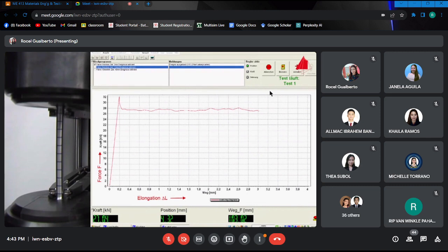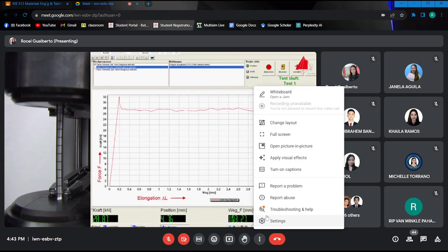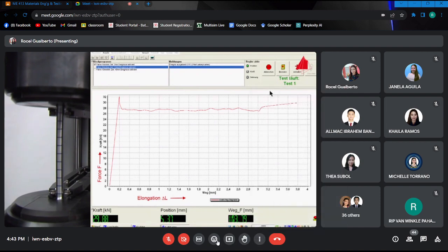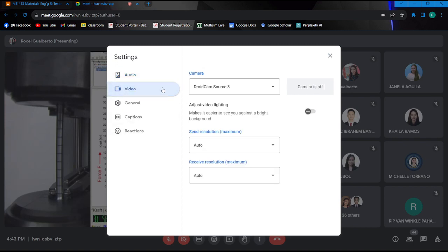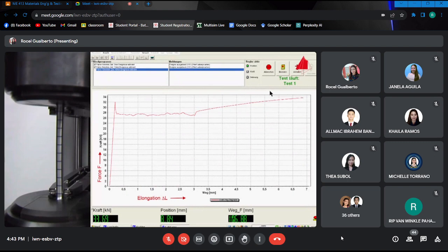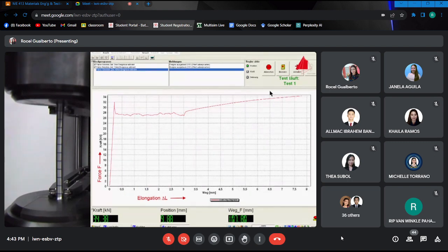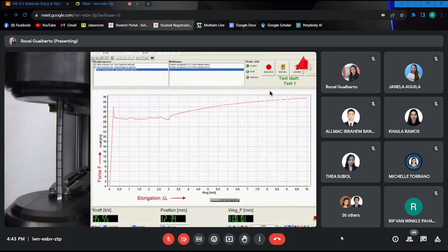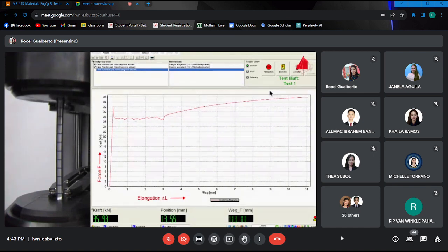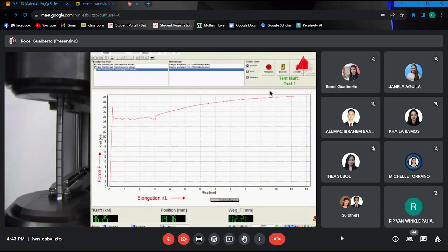After a certain strain, known as the Luders strain, the force increases again. The material opposes an increasing force against the imposed elongation. It strain hardens. Up to the point of maximum force, the test piece is strained uniformly along its length. This means that the test piece gets longer and thinner but keeps a cylindrical shape.